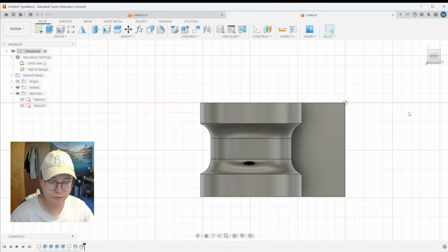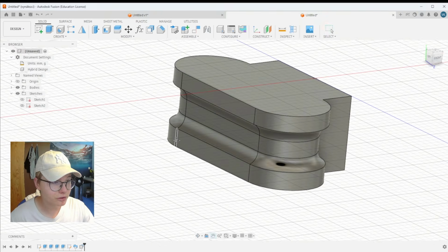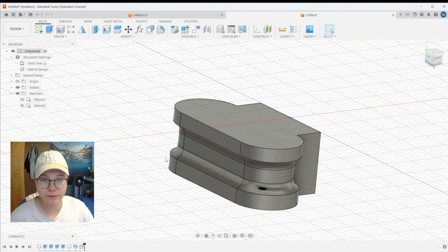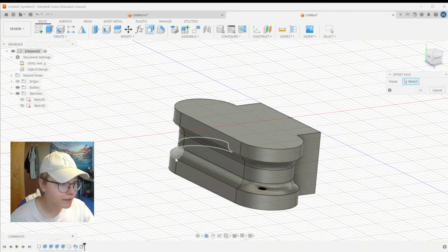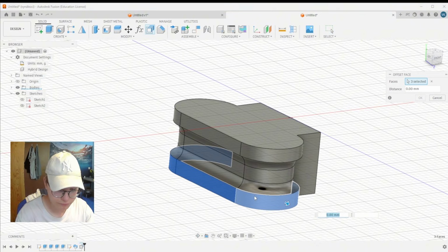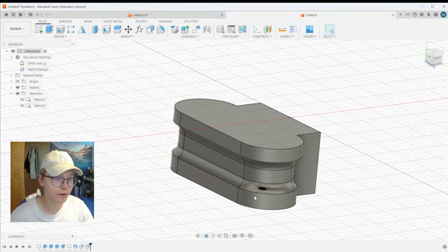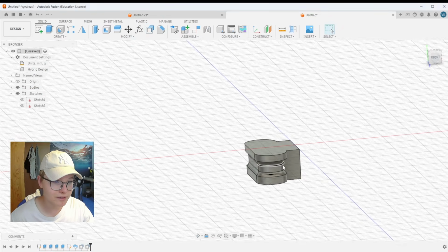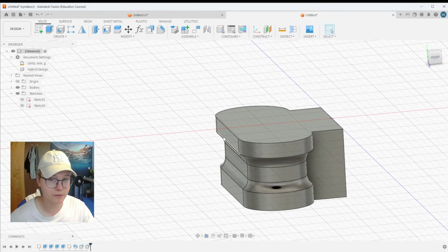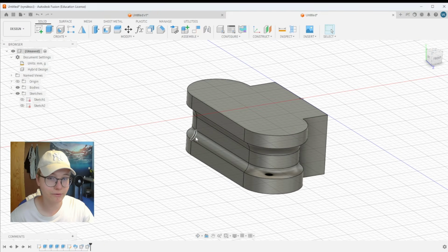This will give it enough clearance to be inserted, but to be able to snap it and then take it out, we need to offset these three faces down over here by an additional 0.15. So minus 0.15, perfect. Now that this is done, this is all that you can do for this part. Now we could start filleting it and doing extra work, but this is really all that it takes for it to work. So I will just stay with that.